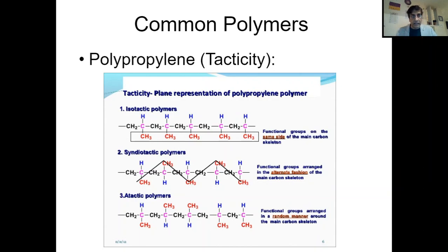This is really important, that's why I made this video. So the tacticity is the arrangement of the pendant group. Remember what the pendant group is here: the methyl group. In case of propylene, the methyl group is the pendant group. In case of styrene, the benzene ring will be the pendant group. So if all these pendant groups are in one direction, then the tacticity is named as isotactic polymer.